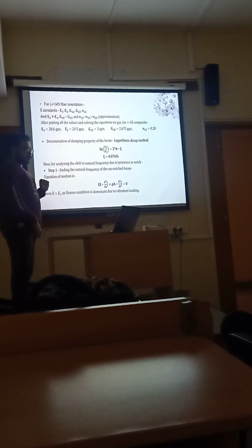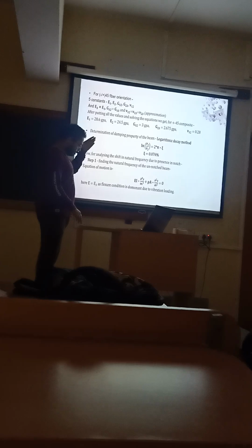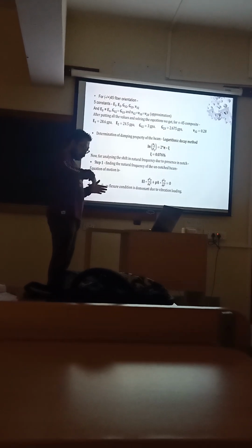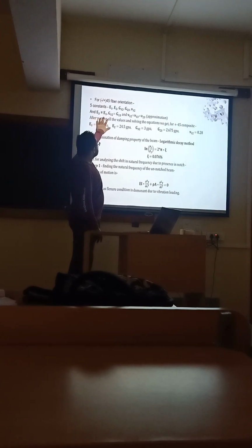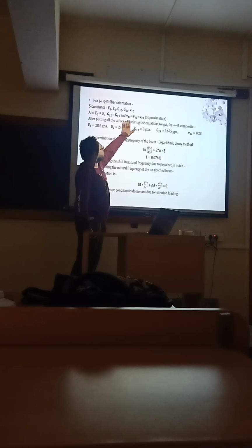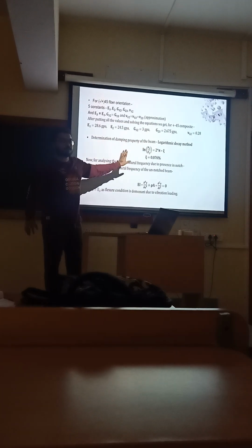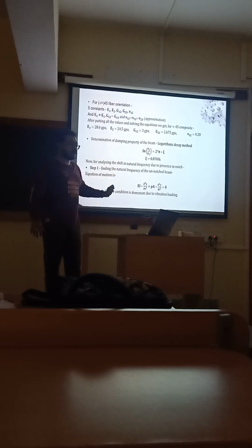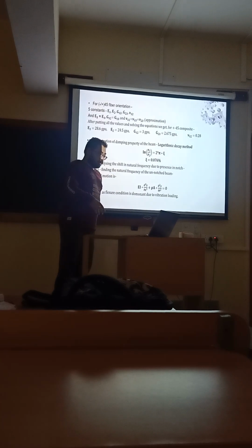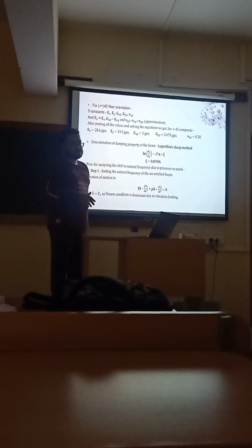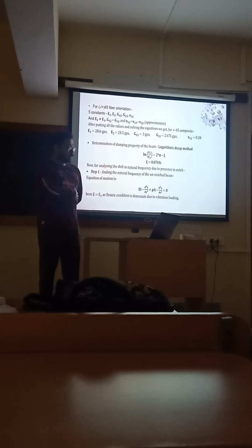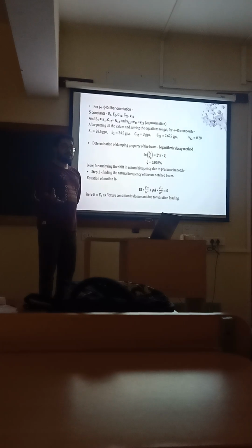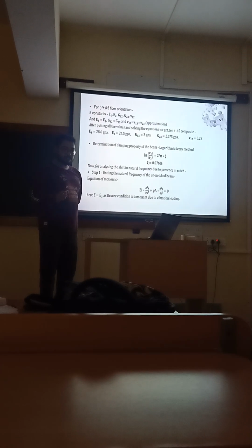Now generally, in the depth, in the z direction, with x, y and z, we have taken E3 equal to E1 and G12 equal to G13. I have taken this approximation for the sake of simplicity of these calculations. The damping properties, since it's a dynamic loading problem, of the beams are found by the logarithmic decrement. Now we have found 9 constants. We have the damping value also there.